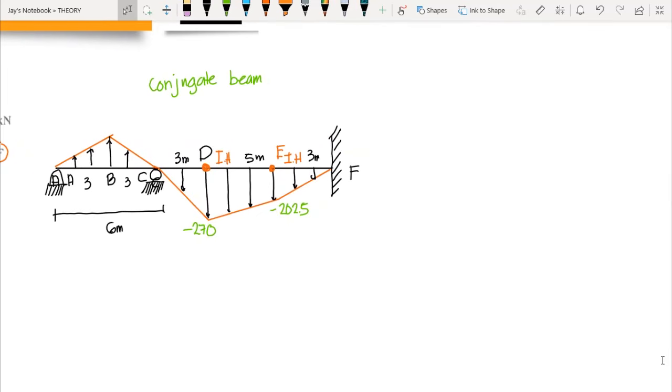Now, our goal here is to determine the deflection at point C. So that means we will be computing the internal moment at C, since deflection is equivalent to moment at that specific point. You can use either the shear and moment diagram, or you can use the moment equation, but to expedite the process, I will be using the moment equation here. Since we will be cutting at point C, that is 6 meters from A, we have to compute the reaction at A at least. We can assume that our A here is going downward.